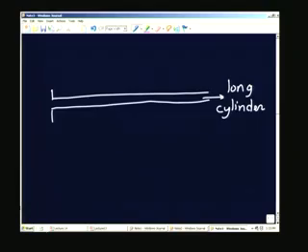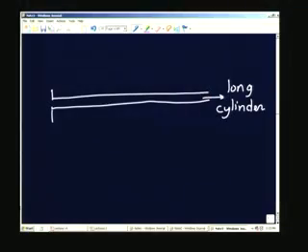So, now let us look at only the conductor. I will remove the outer insulating layer, and I am just looking at the wire, what is going to happen to that. At this place, the measuring junction is there. So, I will just say that is the temperature of the measuring junction, T subscript T. And here there is the ambient at a temperature equal to T infinity.